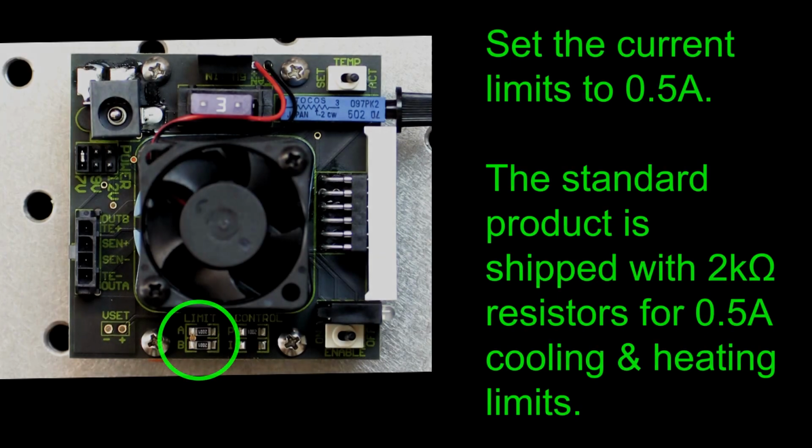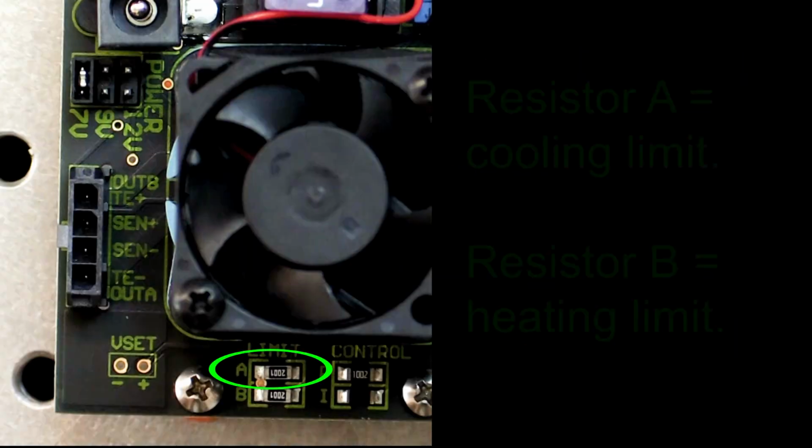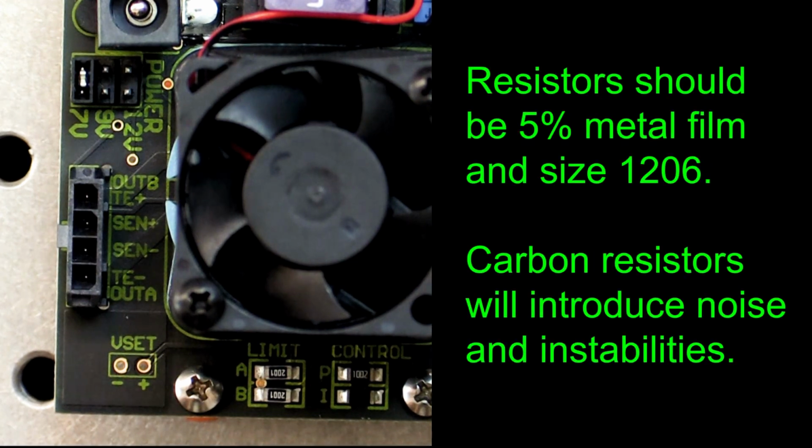Next, to protect the thermoelectric from overcurrent damage, we will set the current limits to 0.5 amps. The standard product is shipped with 2.0 kΩ resistors already installed for 0.5 amp cooling and heating limits. For greater output power, the resistors need to be changed. If you need to do this, be sure to verify your values with the SOA calculator. Resistor A sets the cooling limit, while resistor B sets the heating limit. Resistors should be 5% metal film and size 1206. Carbon resistors will introduce noise and instabilities.